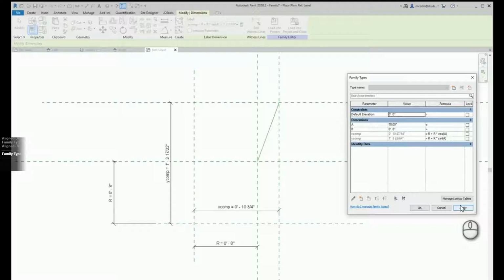If you start to do extrusions and paths that are locked to this constraint, you will still run into buggy performance. And I don't want to oversell the virtues of this. It is basically my experience in Revit that every situation has techniques that need to be implemented for it, and it's been my experience that this particular technique is one that does build robustness with things like door swings and the canopies on a carport. Anything where you've got some inclinations that might need to go beyond 90 degrees.